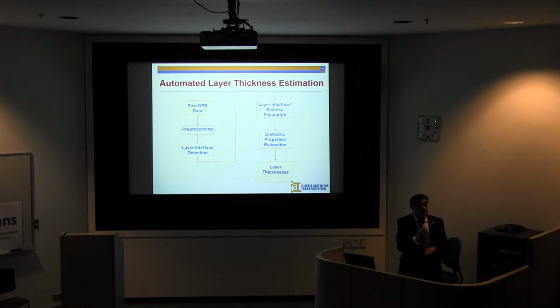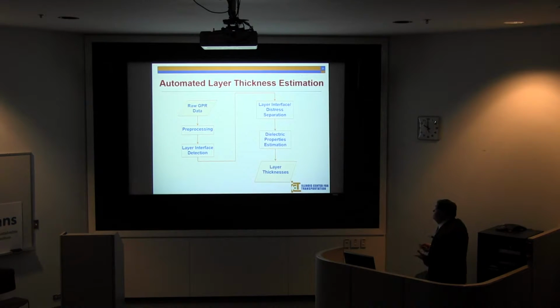If the dielectric constant, which is a good possibility it might be, is the same, the GPR will see them as one layer. Is that clear? So the difference here has nothing to do with the strength. It has only to do with the dielectric constant. That's an important concept about using electromagnetic waves in comparison to mechanical waves.